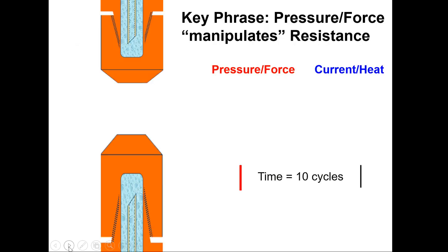So let's have a look at the resistance welding process through its cycle. We have here a few things. We have a cap. And the cap is actually subject to cold water. There's cold water coming down this tube and turning around and going back out. We have to keep these caps as cool as we possibly can for a bunch of reasons. First reason is, of course, it will start to crunch and munch if it overheats. And we need to keep this surface.